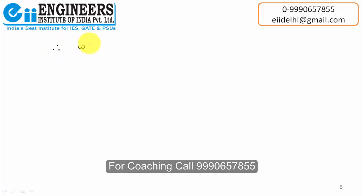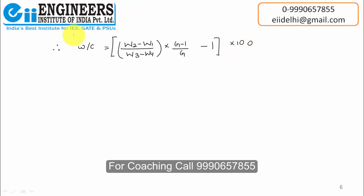So I can finally write that water content is equal to W2 minus W1 upon W3 minus W4 into G minus 1 by G, minus 1, into 100. This is the water content value found from the pycnometer test.